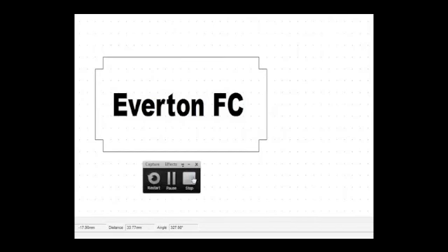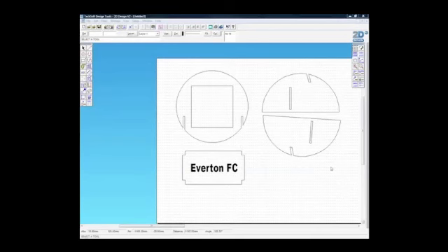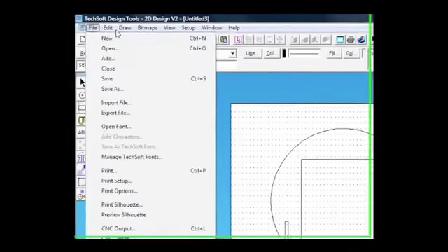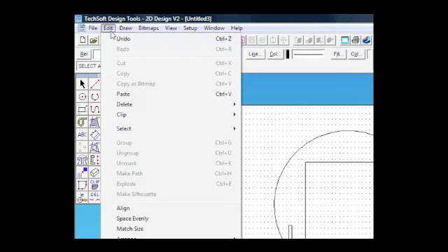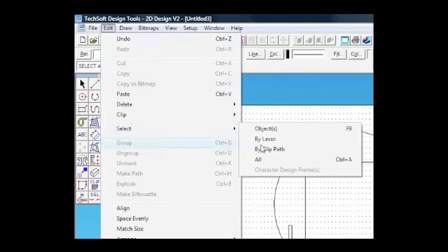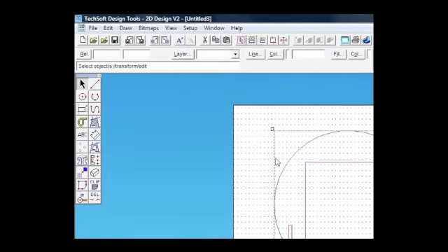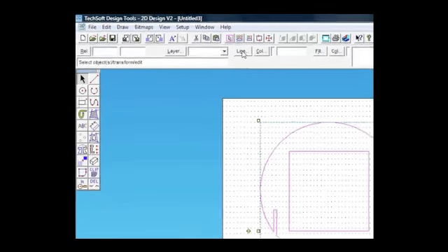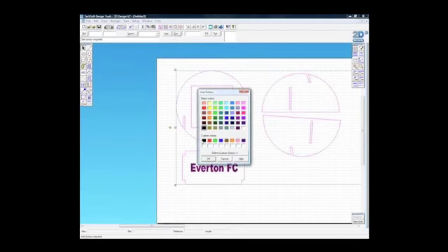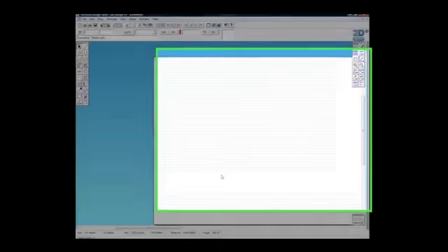Okay, now if we're going to send this to the laser cutter, depending on the laser cutter settings, we will select all and make all the lines red, which is red for cut. We click line, color, red. Okay, all the lines are there and they're for cutting.